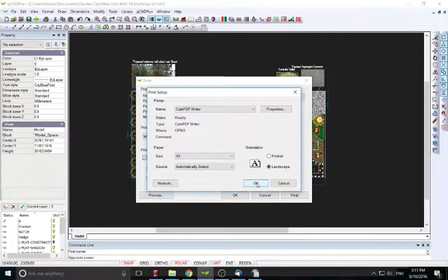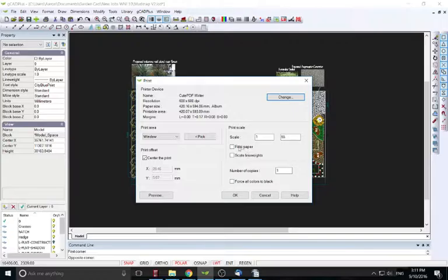This is something to think about. So let's do this A2. Now I would usually go fit to paper, which scales it automatically, but then I usually just click off the fit to paper. What I'll do is change this to a nice even number, rounding up, not down, because if you round down, you might expand the picture outside the frame of the A2. So I'll just go 55 here, and if you get the scaling right, it should be nice and neat. And that's it. Press OK.